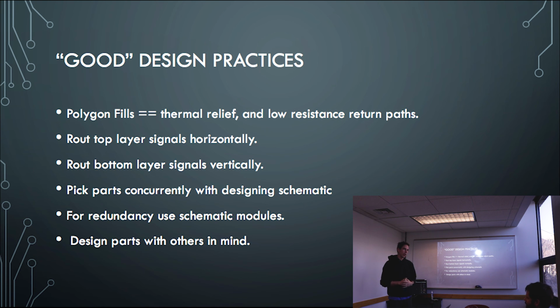Yeah, that's a good question. I think it really depends on the speed of your design and how good the return paths on your ground plane are relative to the power source. This might not be the best answer, but because we've done quite a few simulations, I would simulate the return plane. I'll get back to you on the program, but I would simulate it if I'm having any doubts.